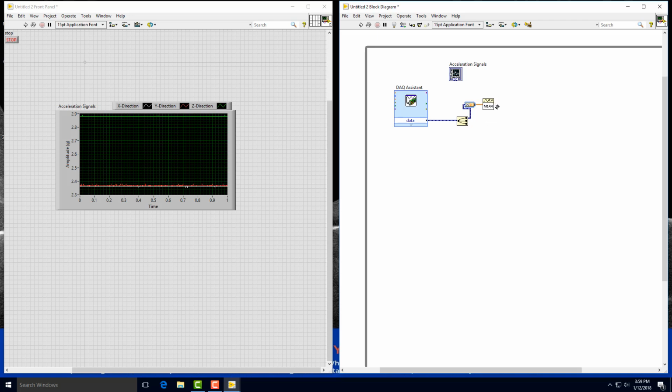So if you see mean has two different outputs, you wouldn't know what they are. An easier way to understand for each tool is to click this show content help and click onto this thing. This means that the blue one is going to give me the error, and the orange one is going to give me the mean value. So in this case, I would like to take the mean value, meaning that I will read this top indicator. That's the mean.